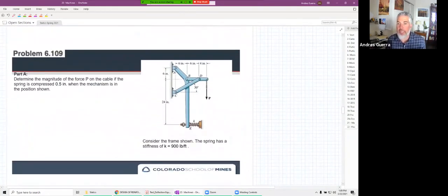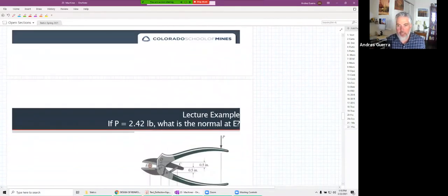We've called it a complete enumeration, but it really works for everything. That's the way that I solve these problems. It's the way that I can look at any frame and say, okay, I know I have my process. As long as I can identify the rigid objects and I know what reactions go at each connection, then I can solve that problem no matter what it looks like.